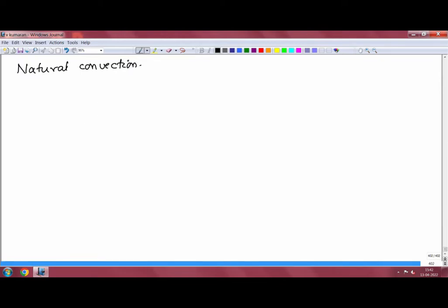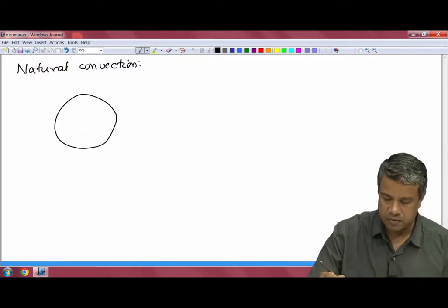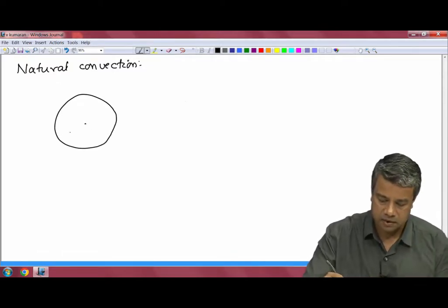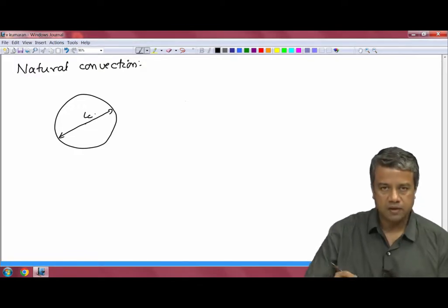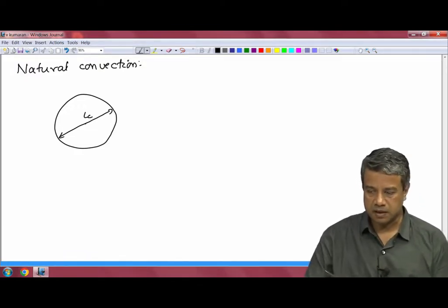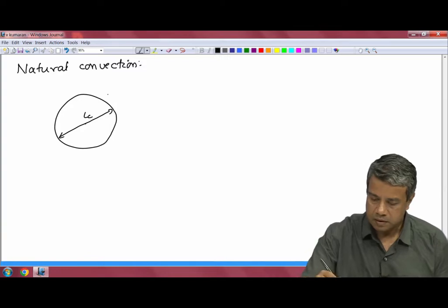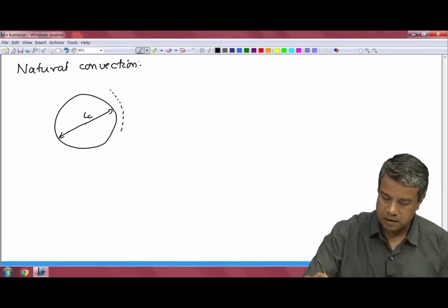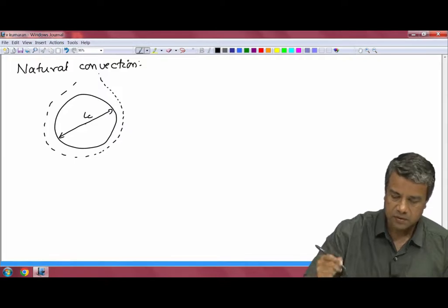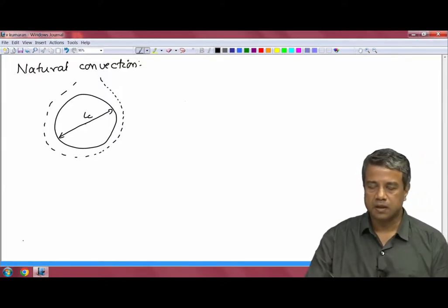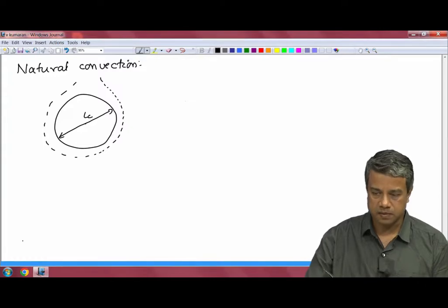In a two-dimensional coordinate system, I had expressed the mass, momentum and energy conservation equations for natural convection in 2 dimensions for an object of characteristic dimension LC, where the characteristic length for diffusion is small compared to LC. Recall that there were 2 dimensionless groups in this problem.